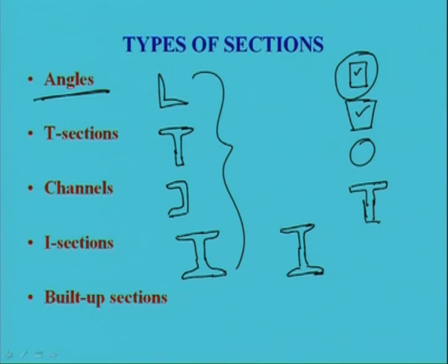Now, for built up section, when the stress is exceeding the limiting value, then what we used to do, maybe these I sections can be added with some plate as per the requirement, either top or bottom or at both we can add some plate, or we can add, say I section is there, we can add some channel as per the requirement, right.